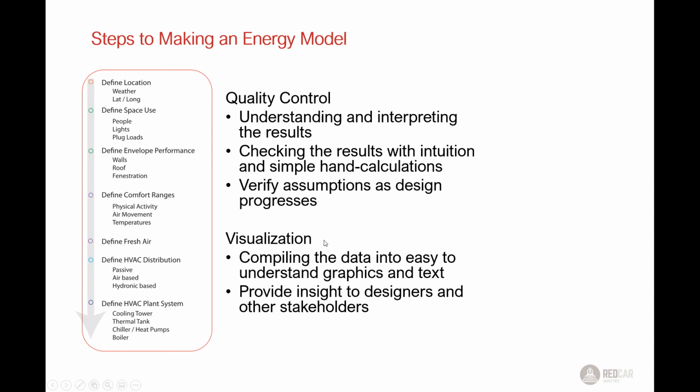I would almost say visualization is a way of even doing quality control, like having enough visualizations of the data coming out and the inputs can be a way to check your model. Simple hand calcs as well, a great way to check. In my climate, I know how many heating degree days there are, and then you can use that plus the envelope to try and estimate how much heating energy you should have with a certain insulated envelope. So there's ways to say, is my number 300% what it should be? That's the real goal of self-quality control, is to get numbers to be within 10 to 20% of where we think they should be.